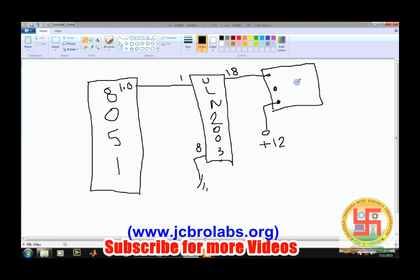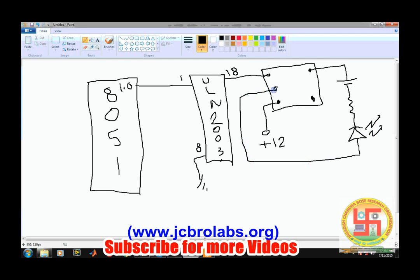And this particular pin, and now we have these two pins. When the relay is off, these two pins are connected, and when the relay turns on, this and this are connected. So we have connected a 5 volt supply, and then through this one we have connected an LED here like this, and the second end of the LED goes here. You can check the previous diagram which we just discussed. In that diagram we connected the LED in the opposite direction. So this is the correct circuit diagram, and here we have connected a 1 kilo ohm resistance, and this is the plus 5 volt. This is just for demonstration purposes.